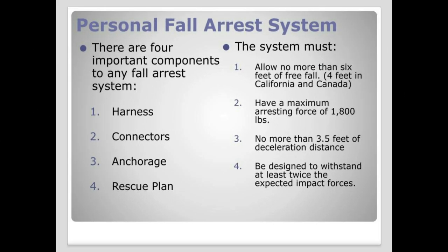A personal fall arrest system. There are 4 important components to any fall arrest system. Number 1, the harness. Number 2, connectors. 3rd, anchorage. And 4th, the rescue plan.